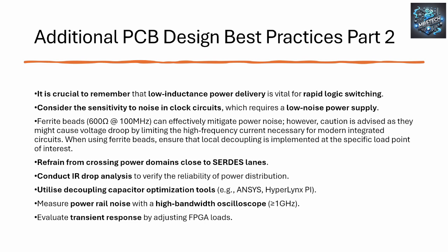So what do you do about that? Well, on the right hand side of the ferrite bead, the one that's connected to the noisy signal, make sure you've got ample decoupling capacitors. That way your ferrite bead is filtering noise, so it's localizing the noise to that small area on the right, but the decoupling capacitors are feeding that high frequency transient with current.